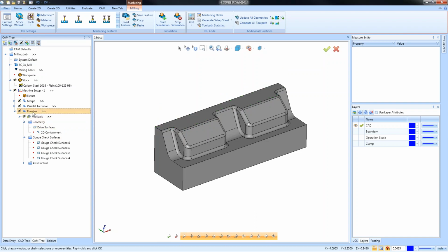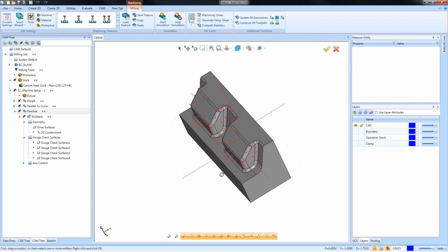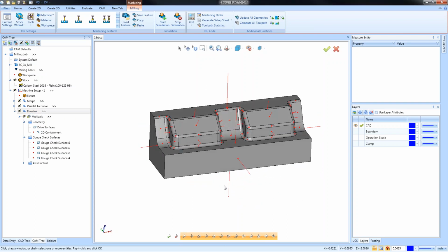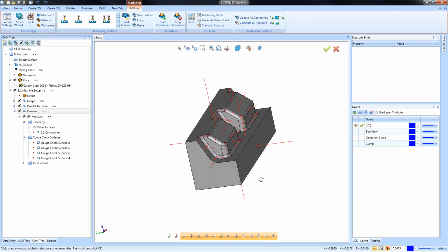Now, the other thing that I want to take a look at real quick that ties into that has to do with surface normals. On your main CAD space, there's this toolbar here that's always here. It's on every system. Everybody's system. You can't remove this toolbar. And this one all the way on the right here says surface normal. If I click this, we're going to see all these little dots, these lines that come up. Essentially, that's indicating the positive direction of that surface, or that surface normal.